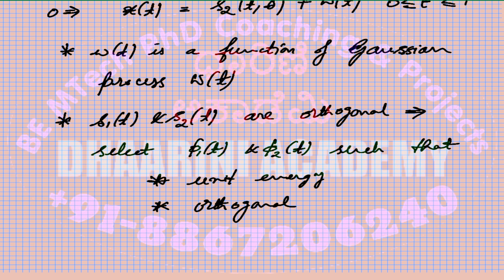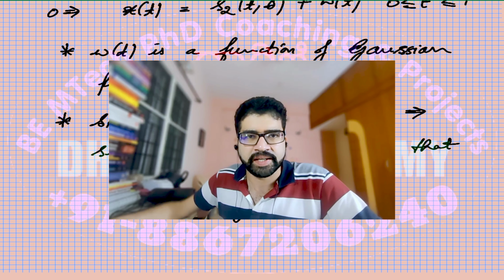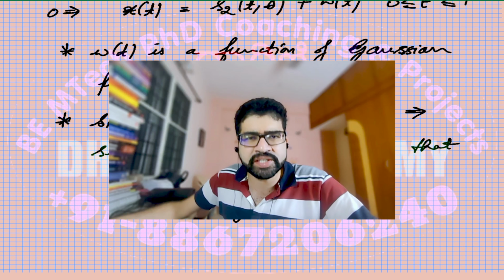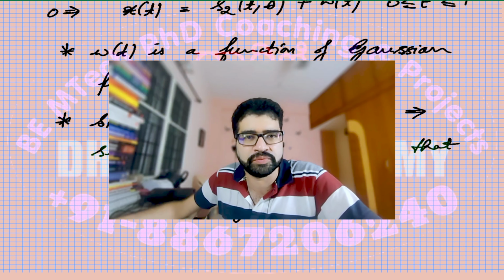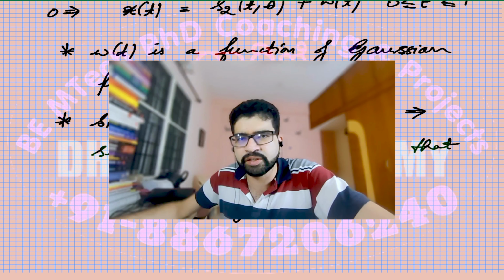Now you see, the phase of the carrier is completely unknown to us. So now we come to the receiver side, and on the receiver side you received the signals, but you have no idea about the carrier's phase, because some carrier frequency is present and it has been changed by a specific value theta by the channel, so we are completely clueless.